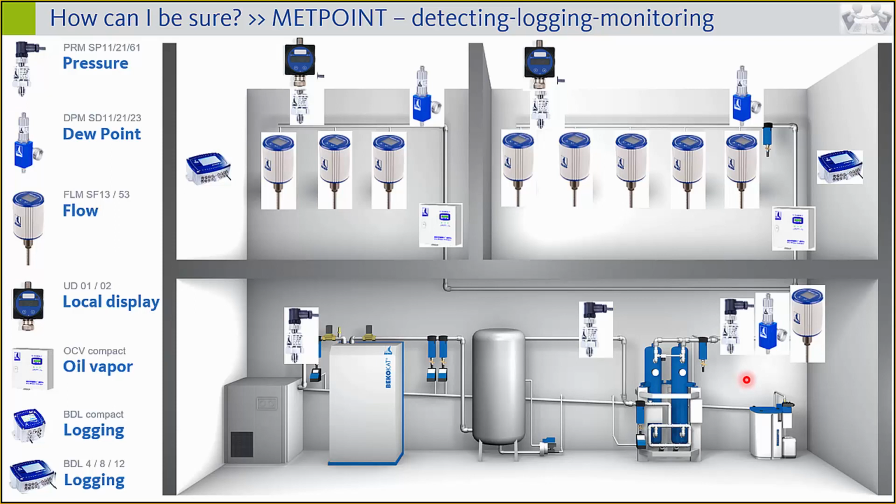It could be end of lifetime of the desiccant, but it could also be that somewhere in the application area, an additional application has been integrated. For example, the compressor and the BEKO cut can stand this higher demand of airflow, but the desiccant dryer was already selected on the edge, and now it is overloaded and will not give you the required dew point. The flow meter installed here will automatically give you a good number to figure out what was going on.